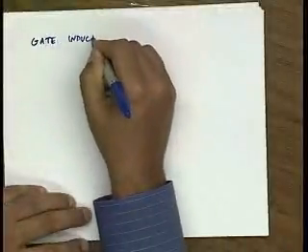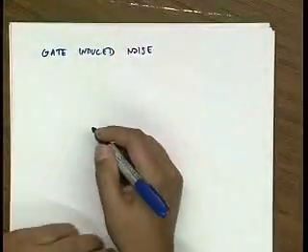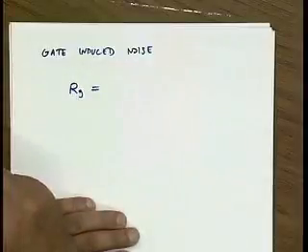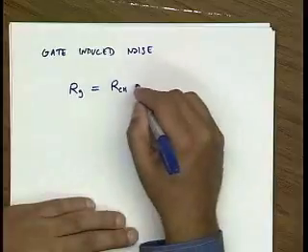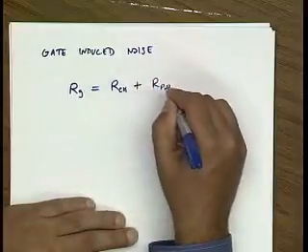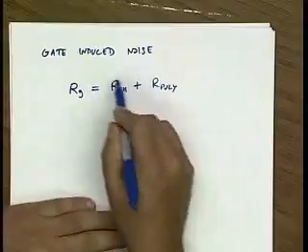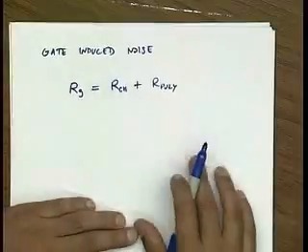It's actually a very nice, convenient thing that happens. If I were to include the gate-induced noise, all I would have to do is say Rg has several components. It has a channel resistance, induced channel resistance, plus, let's say, some poly resistance, right? So I've actually carried along this gate-induced noise with me, but I've ignored the fact that it's correlated, right? That's what should be bothering you.